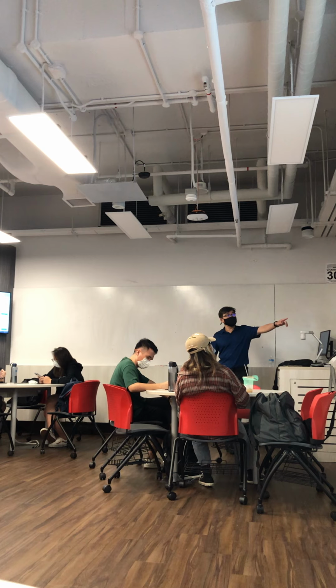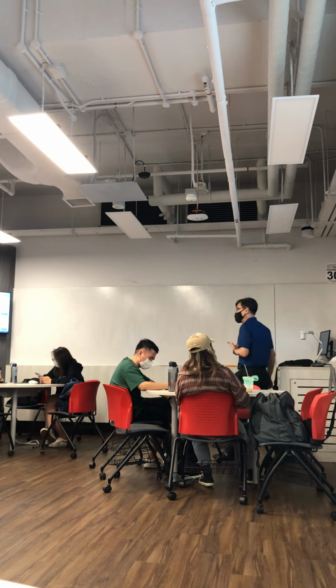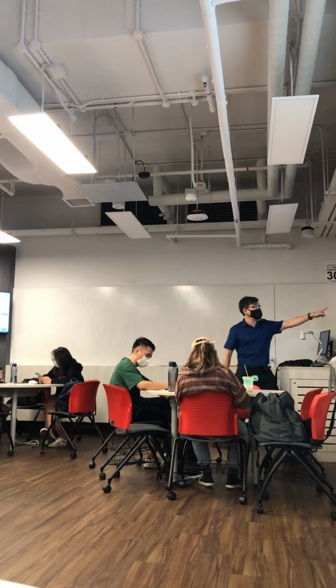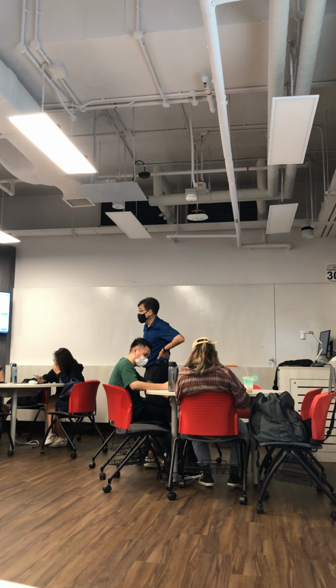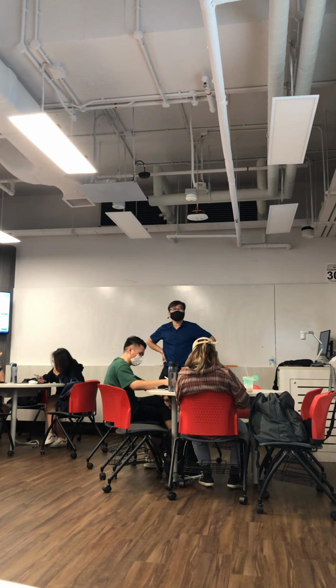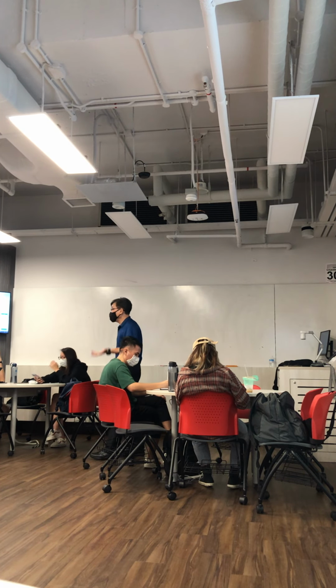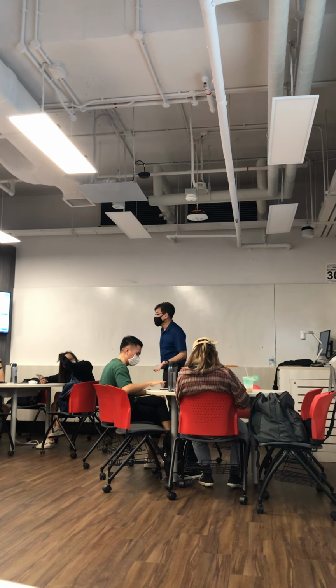This is called the transfer function, and S is the Laplace transform. This S here is actually j omega, where omega is the frequency. And T(s) can be current gain, voltage gain, whatever. It's just a transfer function. A transfer function is something over something.